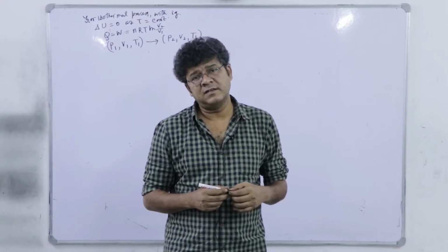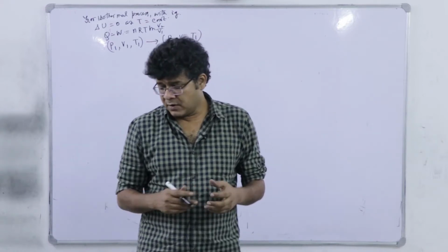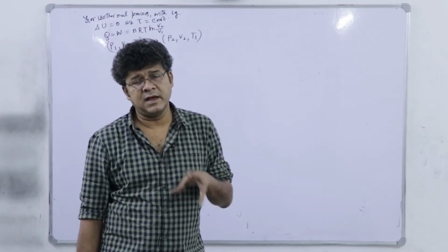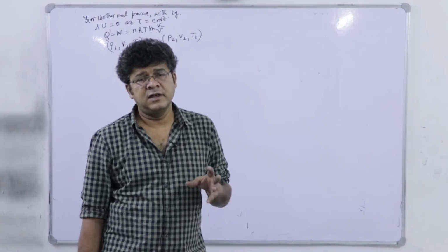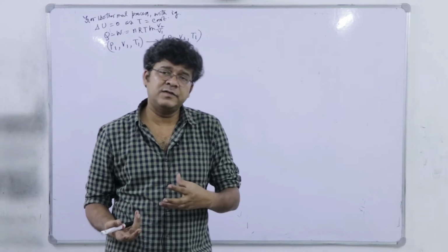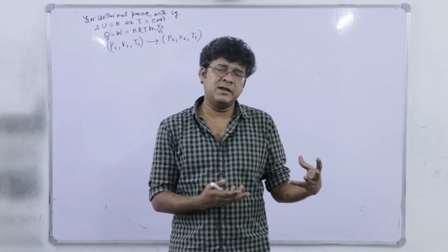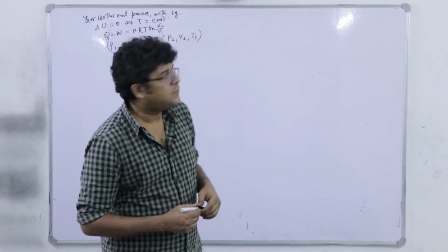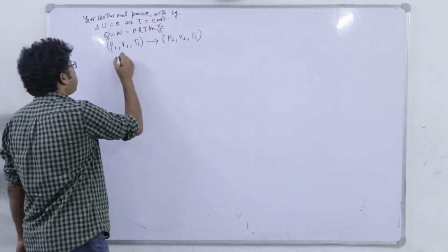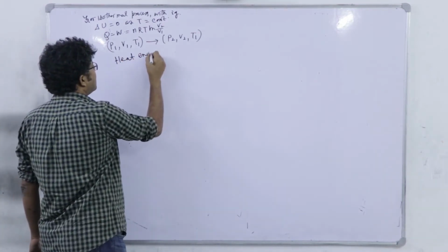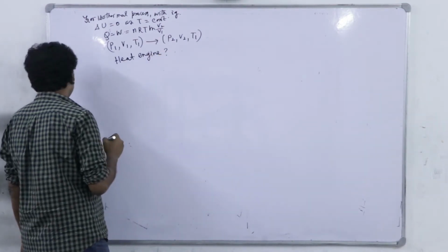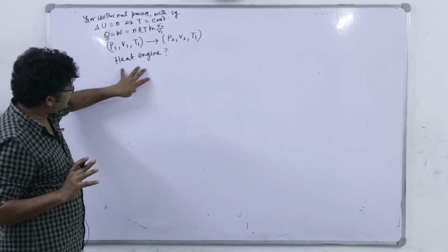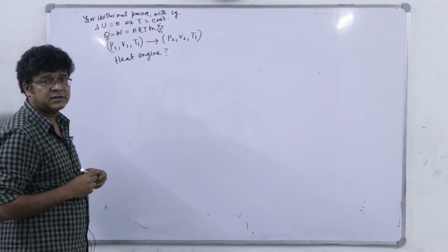of the Kelvin-Planck statement and the Clausius statement respectively, we now go to this understanding of the basics, very basic schematic and the energy transfer operations in heat engine and refrigerator, where the idea of these two devices is built into the first and the second statement of the second law. So, you see, what is a heat engine? Heat engine is a device which takes up heat from a high temperature thermal reservoir.